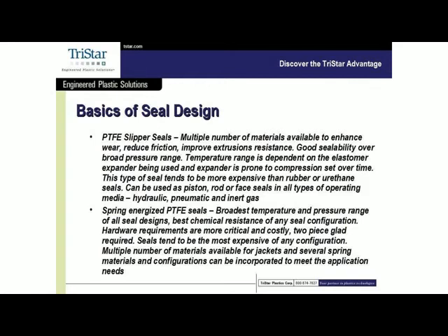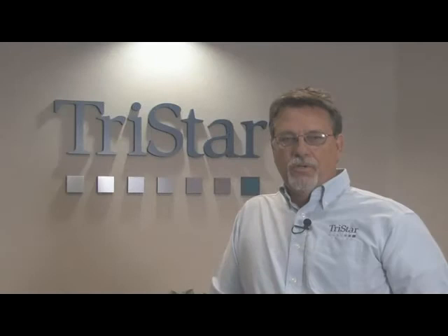These can be used as piston or rod seals, face seals, in all different types of media. Hydraulic, pneumatic, inert gases, some water seals. And then finally, spring energized PTFE seals. This is really kind of where we are specializing these days. It's a very high-end product for very difficult applications.